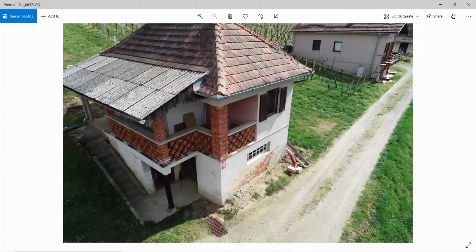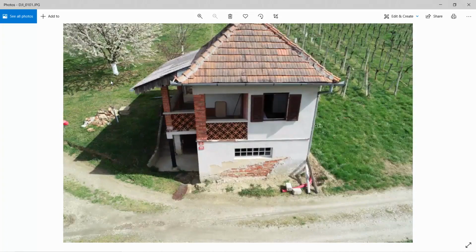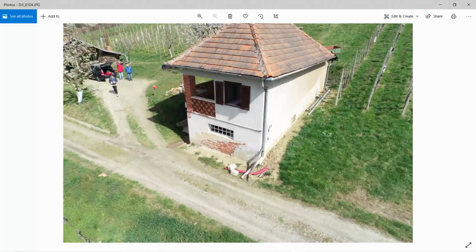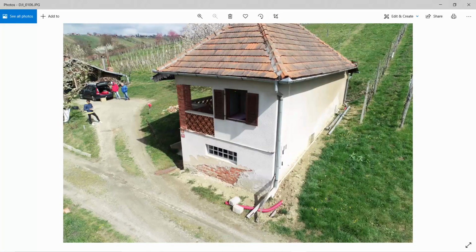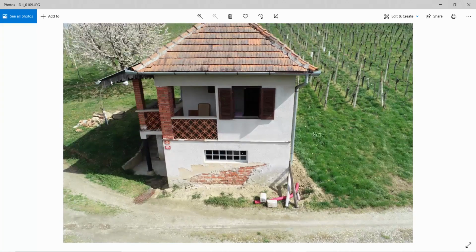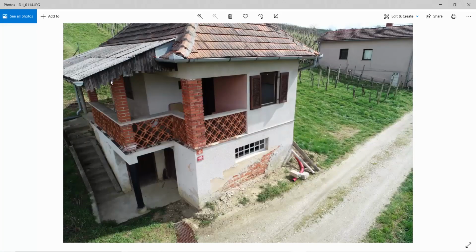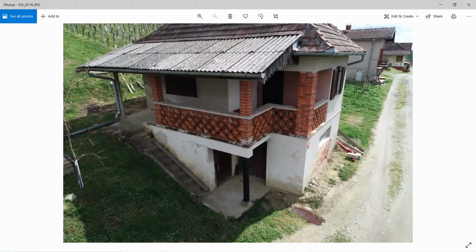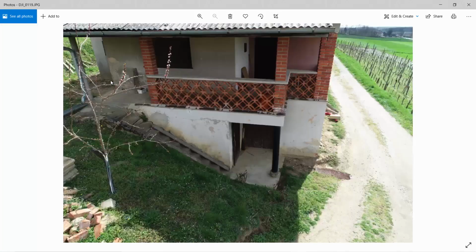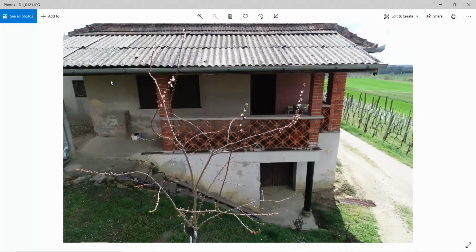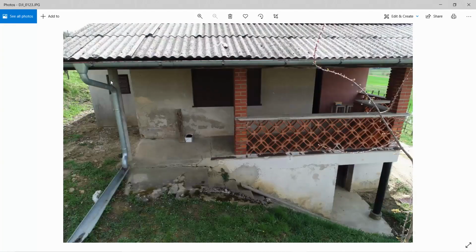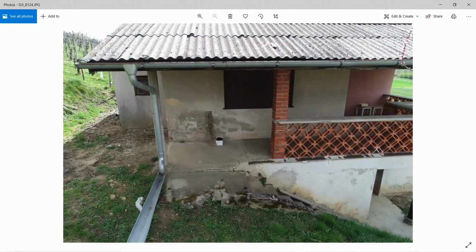These are still drone images. As you can see, I go really low. This is probably 7 or 8 meters height above the terrain. What's super important here is, if you'd like to successfully combine phone images with your drone images, you need to get a pretty similar perspective from the starting point.